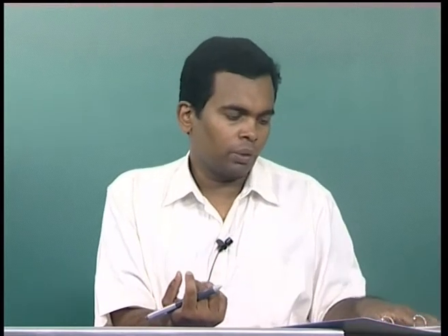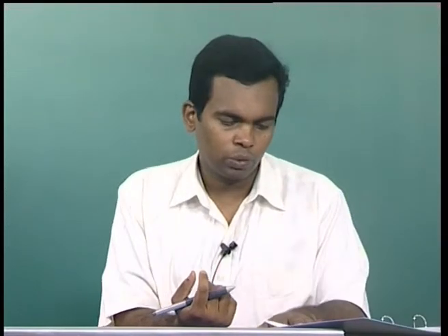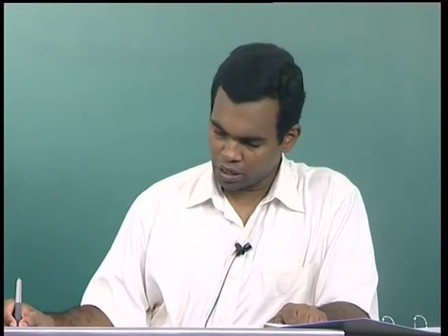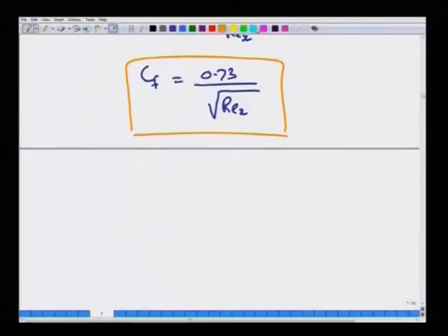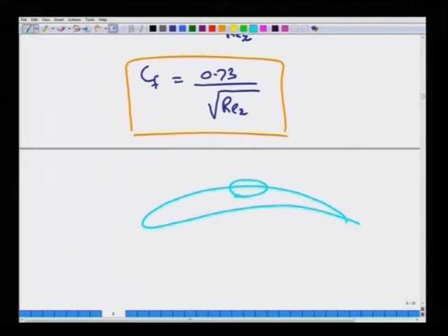Okay. Now, the same thing can be carried over to more complex objects. Here we took the simplest possible case, namely force on a flat plate. The same thing is valid if you consider even an airfoil, because locally the boundary layer is actually flat. So, you can integrate over the contour of the surface to get the drag forces.